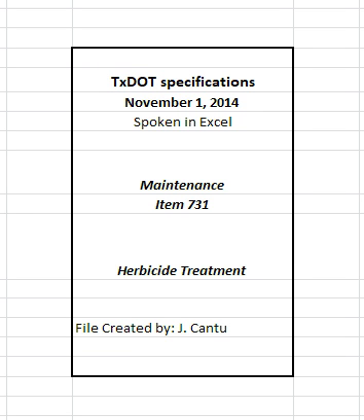7.5 Wick application. Apply herbicide to targeted vegetation within the full width of right-of-way, excluding areas as shown on the plans, by wiping the rope wick applicator across the vegetation at a constant rate in a smooth manner. Adjust wick height to achieve the control of only the targeted weeds. Apply herbicide only to target weed species as shown on the plans, or as directed. Replace any desirable trees, shrubs, wildflowers, or grasses damaged by negligent applications. Retreat all target weeds not controlled after 15 days until weeds are controlled.